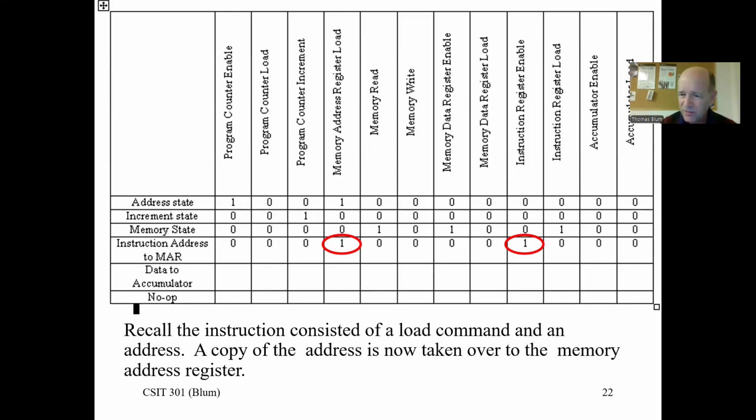We want that to come out of the instruction register and onto the bus. So that is an enable. And then in the memory address register, again, that piece of data was an address, so we wanted the memory address register, and so that is a load. And so that was our first step of the execution cycle, those two ones.